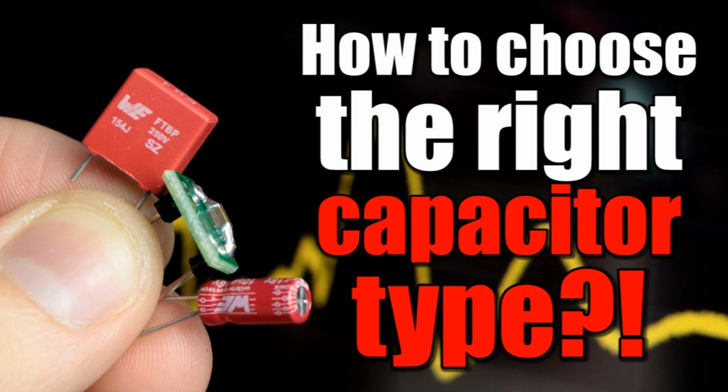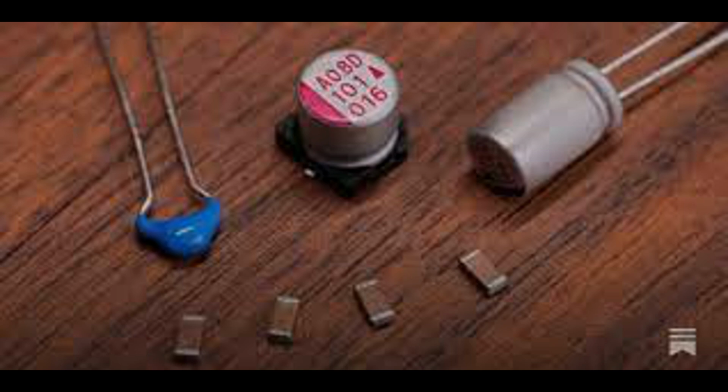The amount of energy a capacitor can store depends on its capacitance, measured in farads, and the voltage applied. The energy stored in a capacitor is given by the formula E equals 1/2 CV², where E is the energy stored in joules, C is the capacitance in farads, V is the voltage across the capacitor in volts. Applications of capacitors for energy storage.